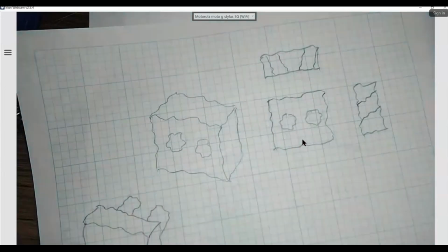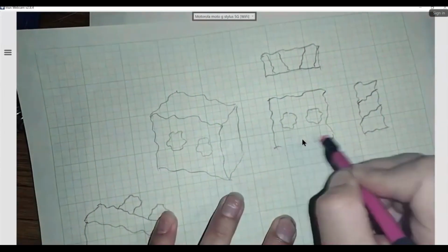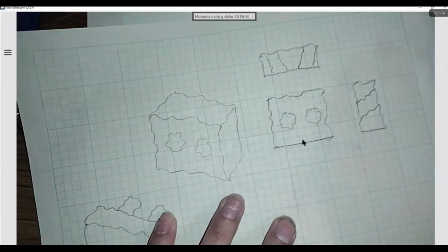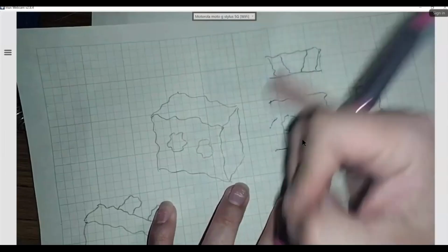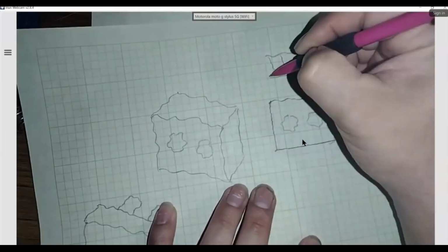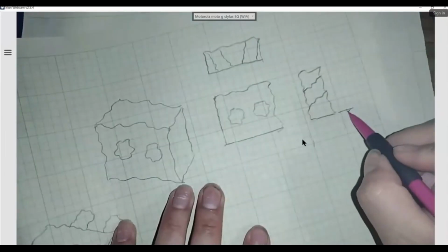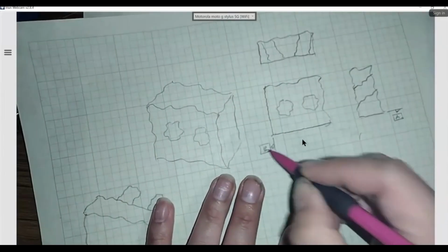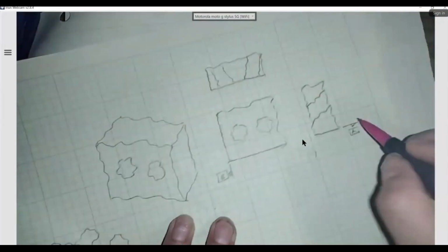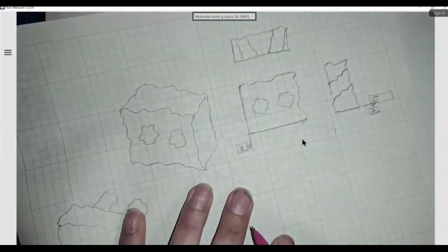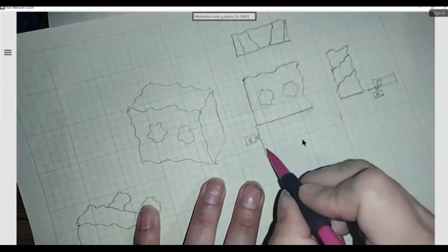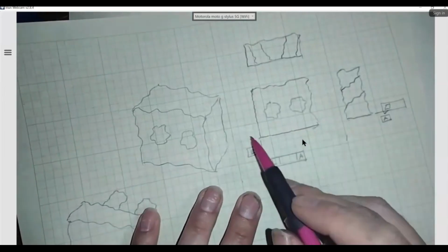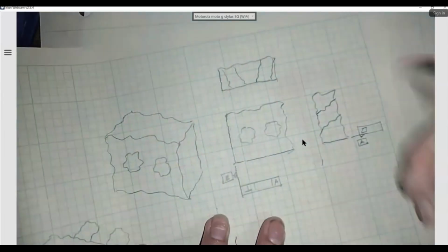So I am first going to establish my reference frame. Let's do our typical: I'm going to try to control the surface, the bottom. I can also try to control the left side, to make it a little bit less crooked. Let's define datum A as the bottom, and let's define the left side as datum B. Let's refine datum A by adding flatness at the bottom, and let's refine datum B by making it perpendicular to datum A. That's why A and B become perpendicular to each other. Let's also refine the back.